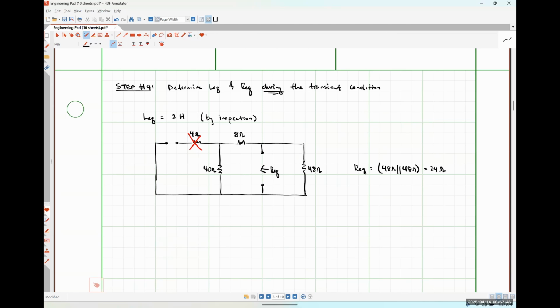I wouldn't say make it open circuited at all of the resistance. So this is where it gets a little potentially tricky, okay? So for a first order circuit where it should be fairly obvious if your inductances are connected in series, parallel, or something like that. And we'll work some example problems later on, particularly on Friday, that'll show us more what to do there. But essentially, if we can easily see how our inductances are connected, that'll make it easier. If we only have one resistance, then obviously we could just take that resistance out. It gets more complicated when we have several resistances and several inductances.